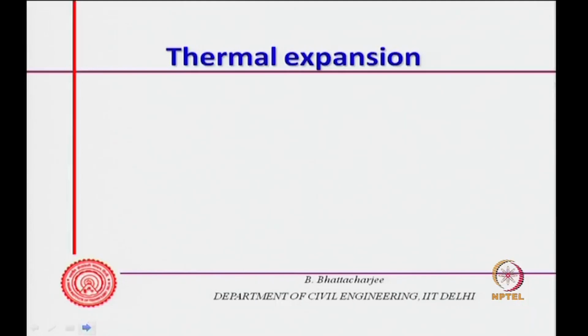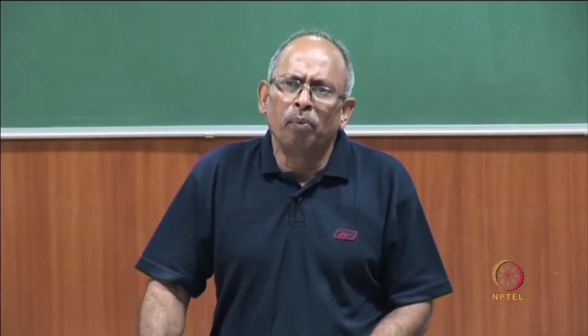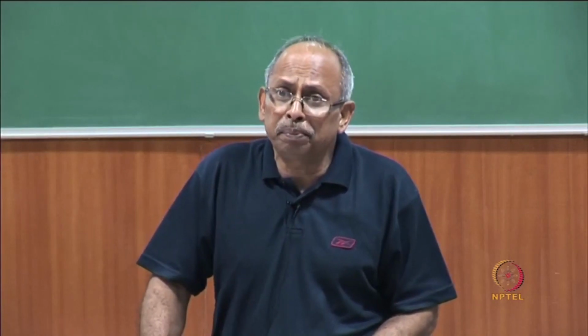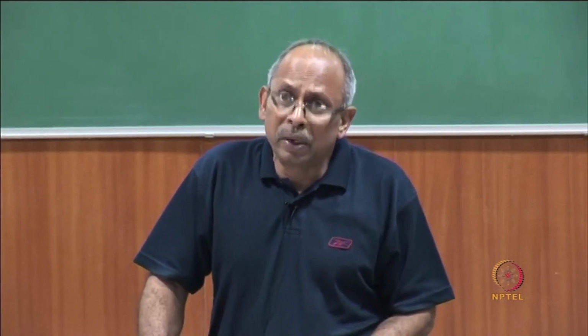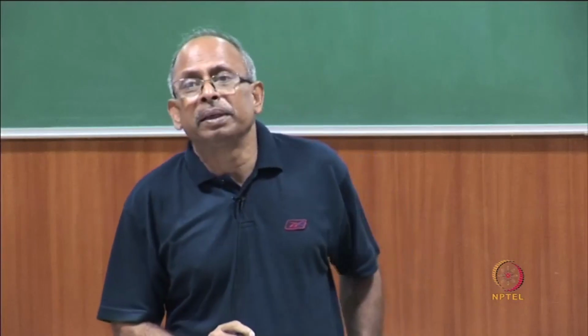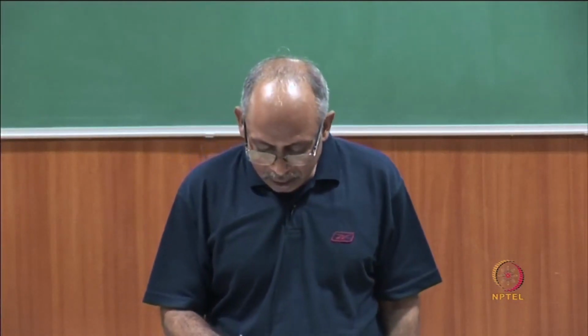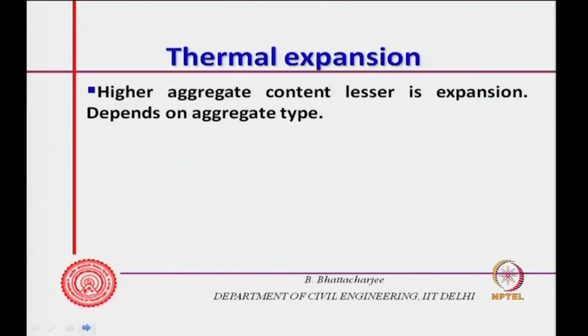Now, next we can look into thermal expansion, which is almost a related matter to shrinkage, because this is also a kind of dimensional change. And you see the coefficient of thermal expansion is important because, for example, if I am using a reinforcement, let us say steel, its coefficient of thermal expansion should be similar to the concrete.